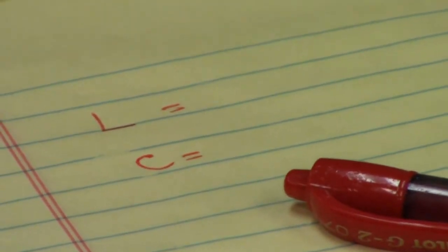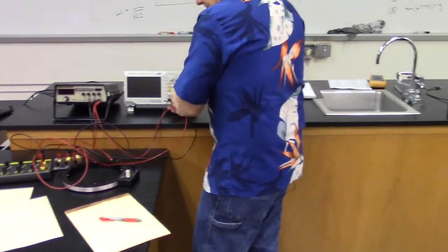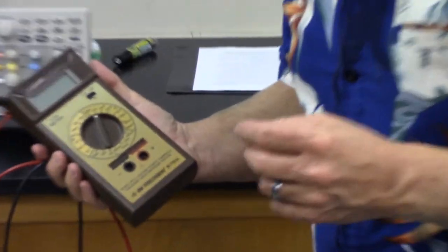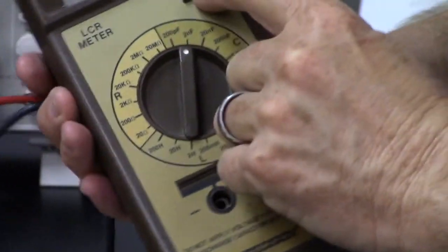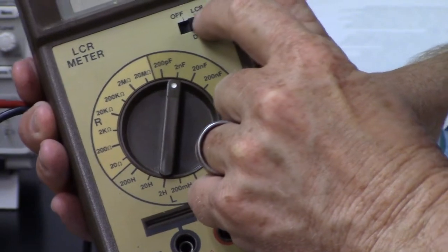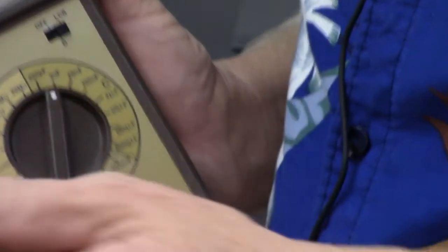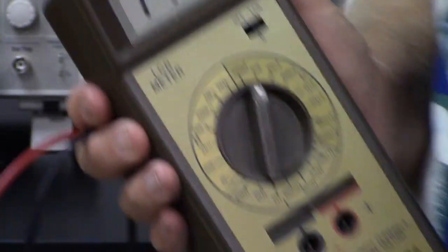All right, well, to do that, maybe I will power down my equipment, and the first thing I will do is grab my inductor. And I guess I'll need a couple of wires to measure it. And I will grab the LCR meter. I think the only time we used this was way back when we were doing capacitors. It's in the off position. If you click it all the way over to the LCR, that's why it's called an LCR meter, L for inductance, C for capacitance, and R for resistance. And by the way, this one here is to test D for diodes, which we've had somewhat of an introduction to